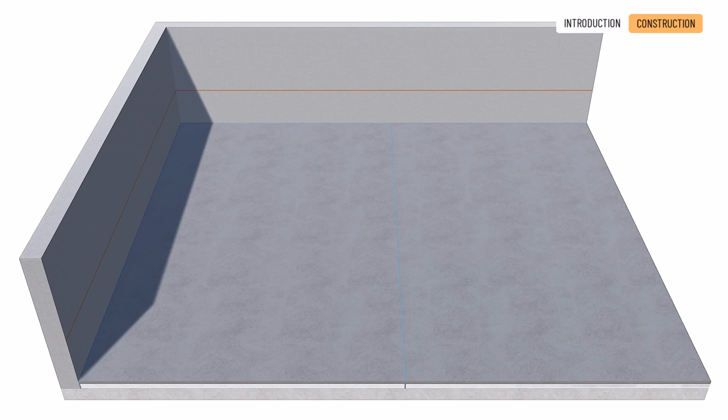The procedure is similar when constructing a cement screed. The main difference is that the fresh mix is prepared on-site using a mechanical mixer and applied with a pump. The typical layer thickness in this case is 2 to 5 centimeters.